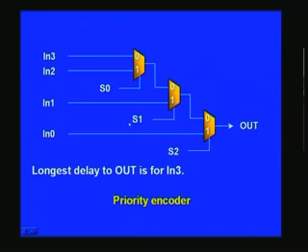On the other hand, if you go to selection of input 1, then it has to go through 2 mux as such in order to appear at the output. So is the case with this, and one of these will be the longest path that you will encounter, and that is how you get a priority, but the price that you are paying is 3 delays as such. 3 mux delays are coming into the picture here.